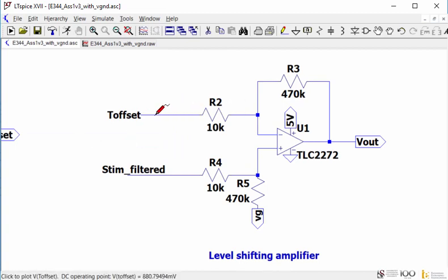Maybe let's talk about the DC offset first. If I don't take out the DC offset, that's the 880 millivolts DC offset on my input. If I don't take it away, then it will result in a big amplification of that DC voltage, which would blow the output right into the rail voltages as far as it could go.